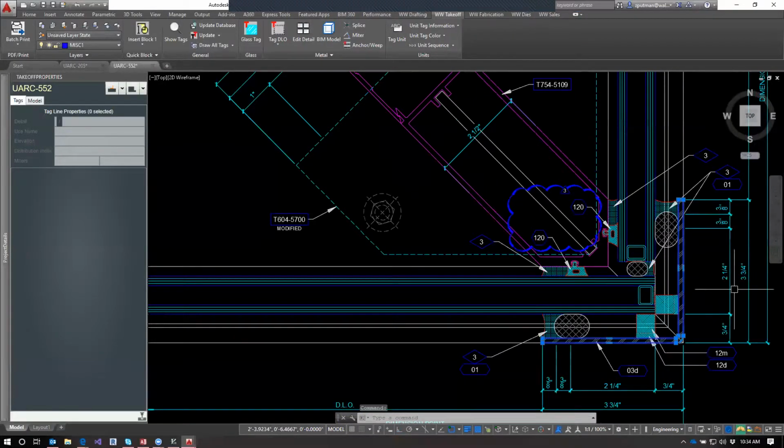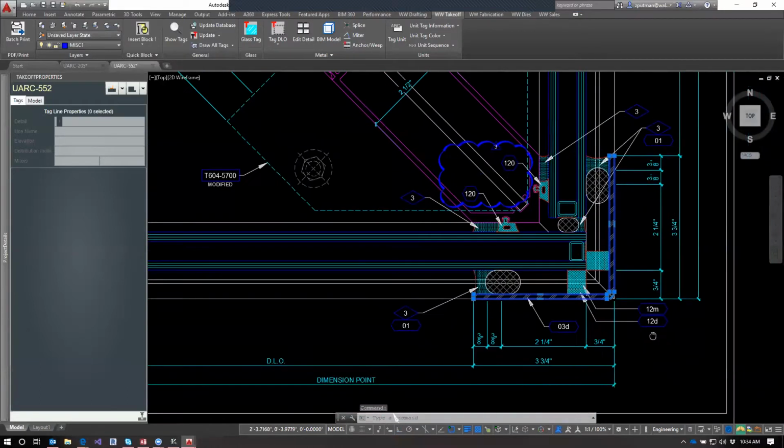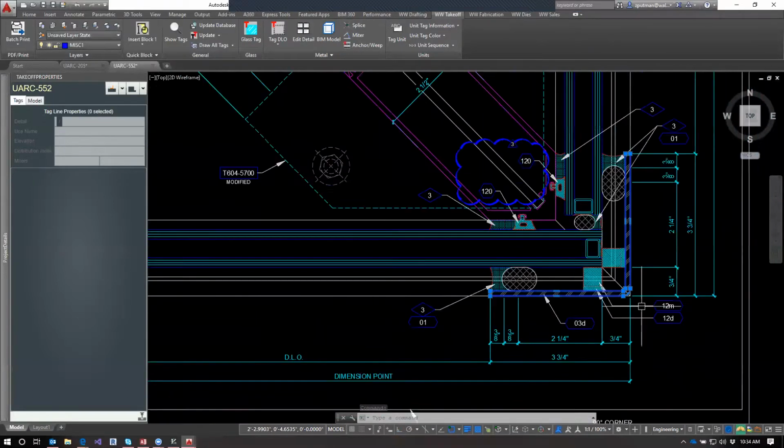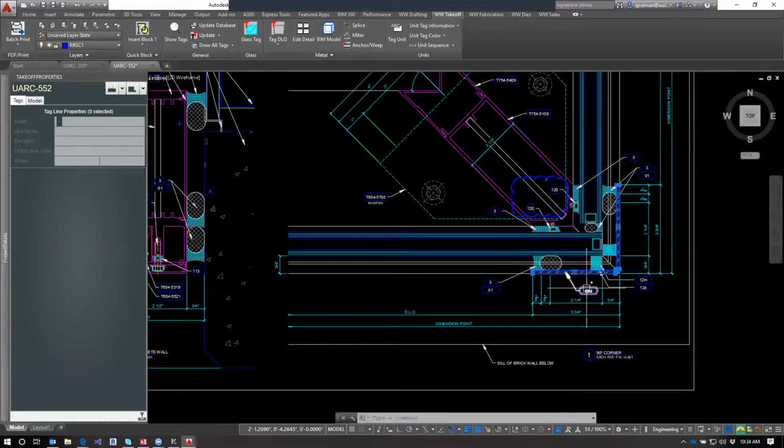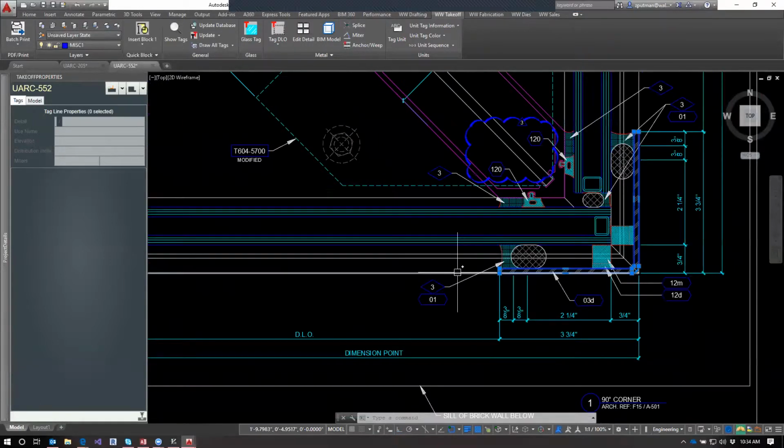You also have this sort of break shape piece out in front. So again, you have a choice of where you want to run that. I'm not going to put that in this vertical. The main reason for that is this piece is going to run between the sill and the horizontal, and then between the horizontal and the next horizontal, and then the horizontal and the head.